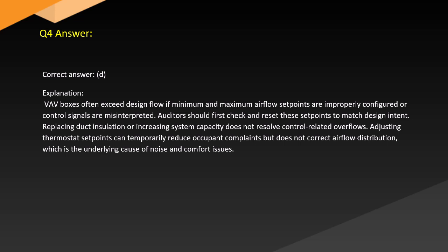Replacing duct insulation or increasing system capacity does not resolve control-related overflows. Adjusting thermostat set points can temporarily reduce occupant complaints but does not correct airflow distribution, which is the underlying cause of noise and comfort issues.